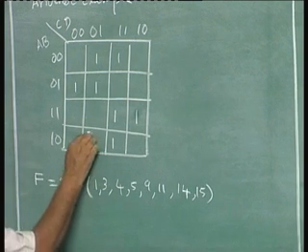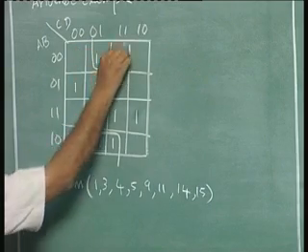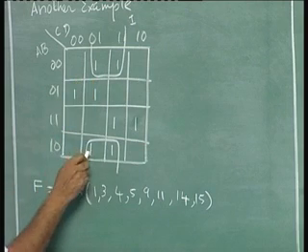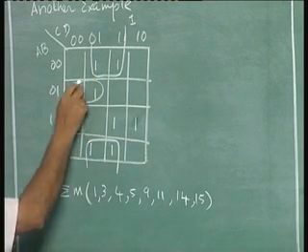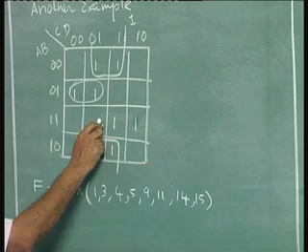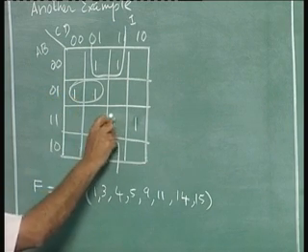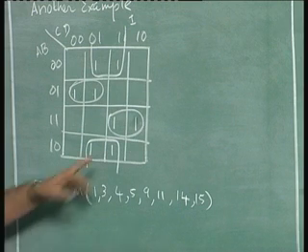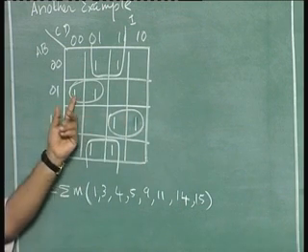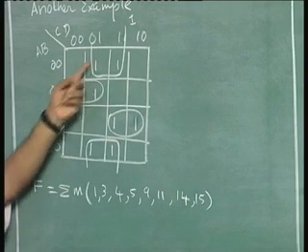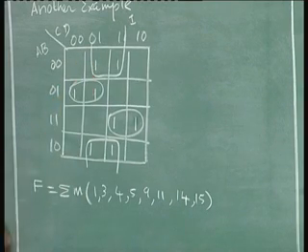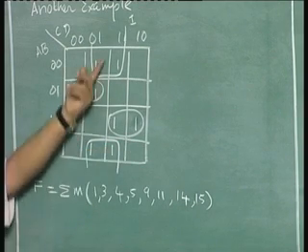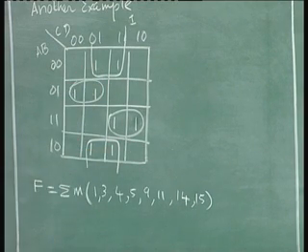So this is my prime implicant 1, essential prime implicant here, these two. So this one cannot be combined in either way. This is another essential one. This is the most efficient way of combining, because this one has to be combined. So this has to be there. This one has to be combined. This has to be there. I could have combined this way, but it's not necessary because I already taken this one into account. And these 4 ones form a prime implicant.